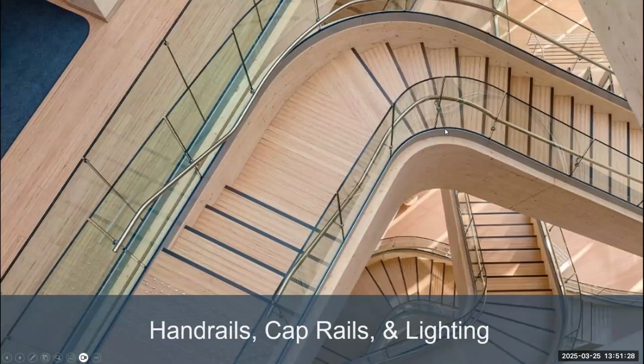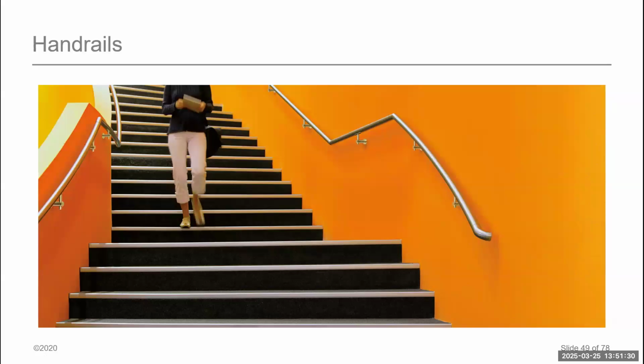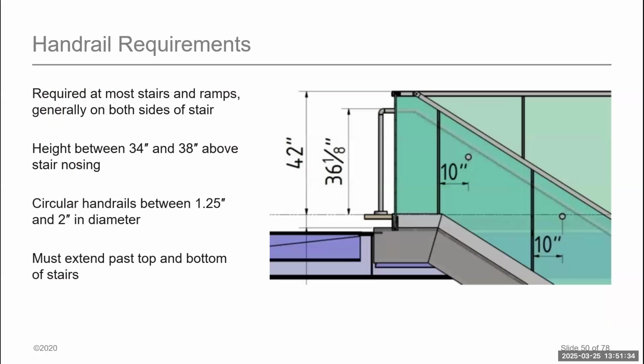The other thing that we have in glass guardrail systems is the overall accessory components, one of them being handrails that we will most commonly see in stairs and ramps, right? Such guardrails need to be mounted at between 34 and 38. We typically design at a standard of 36. And then that allows, when we have some of those varying runs where we need to get down to the landings, we can land in between that 38 and ensure that we stay within the code, right?